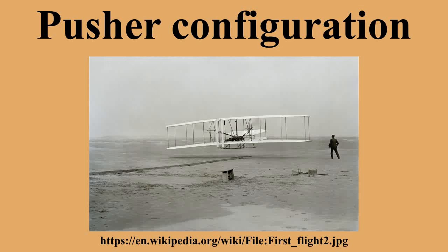Center of gravity and landing gear considerations. To maintain a workable CG position, there is a limit as to how far aft an engine can be installed. The forward location of the crew may balance the engine weight and will help determine the CG, as the CG location must be kept within defined limits for safe operation. Load distribution must be evaluated before each flight.